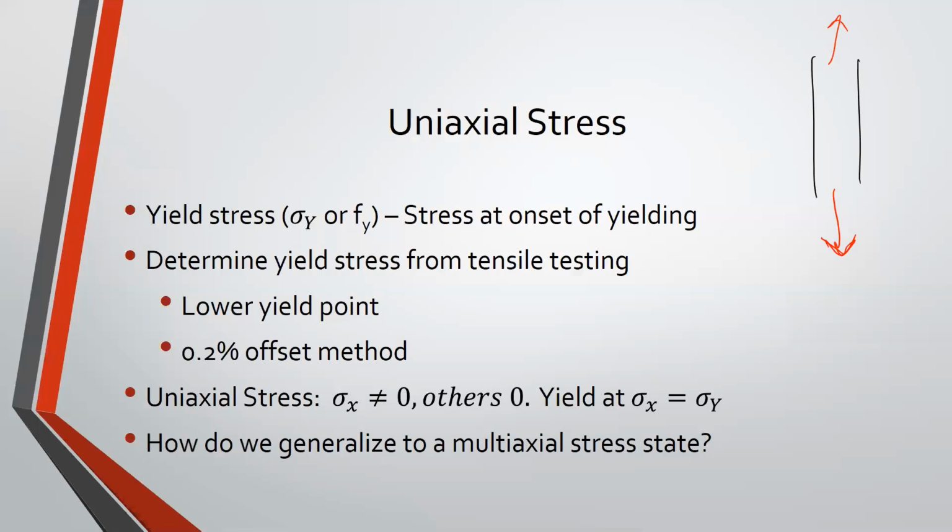When the stress in that material, because we only have one value of stress, equals the yield stress, so when F over A, this is F, when F over A equals the yield stress, we say that material yields. And for uniaxial loading, that's fairly straightforward. But it becomes a lot more complex when you have biaxial yielding, because what you'll see is that we might actually have yielding occur before any of the stress components reach yield stress.